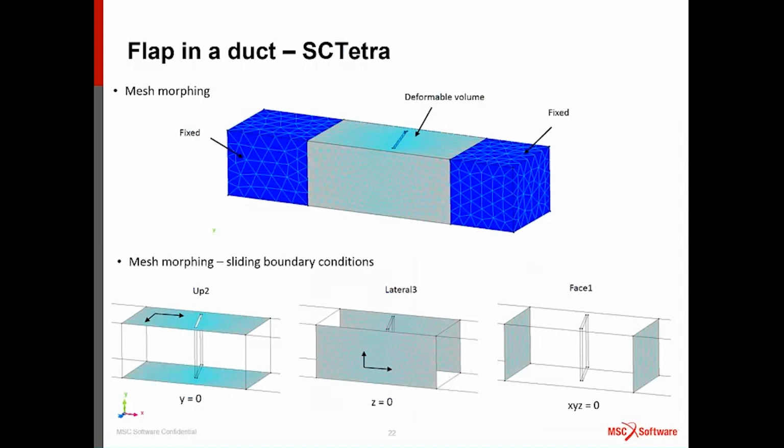Before going through the demo, I want to show you how to create boundary conditions in terms of CFD domain morphing. Since I have a very small gap between the wall on the bottom and the slab, I want to allow the nodes to move on these faces. So I'm constraining only the Y direction. In these other surfaces, called lateral free, I am letting nodes move in X and Y, constraining only Z. And for these two other surfaces, I am constraining everything. I could change this and see what happens.